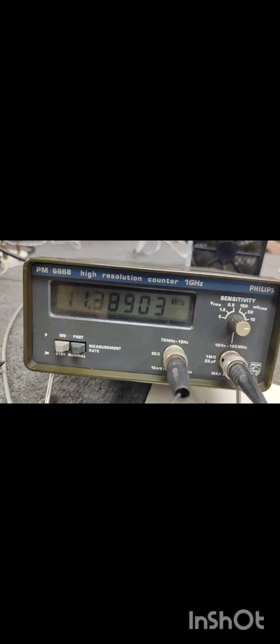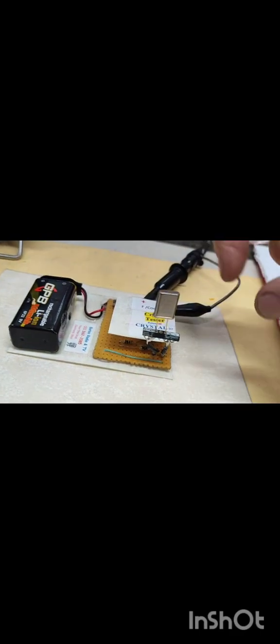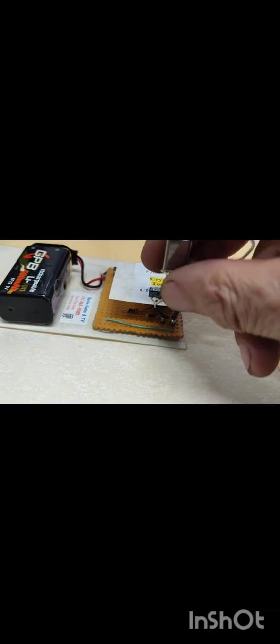So it is very close to 139, which is perfect, as I said, due to the stray influence of the test jig, the socket and so on, because I made it universal for different spacings. I could have made it a bit smaller and shorter, but this way I'd rather sacrifice 10 hertz on 14 million than battle with the crystals, to be able to test them quickly.